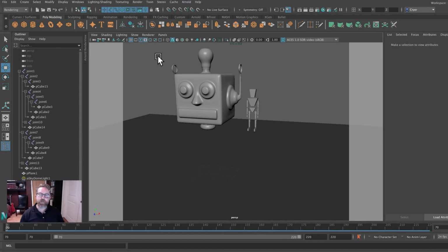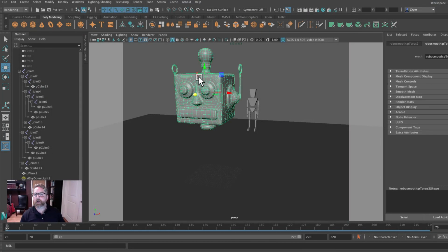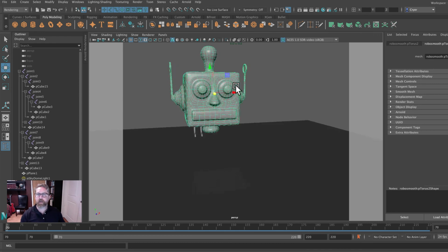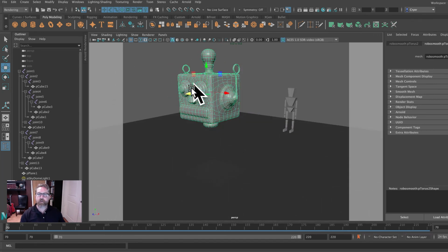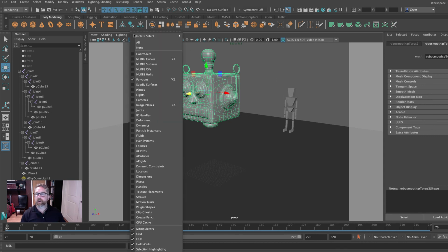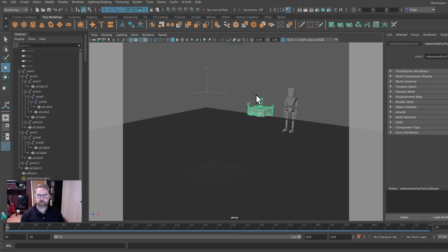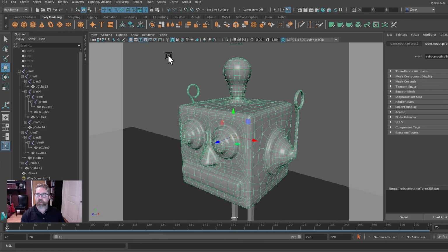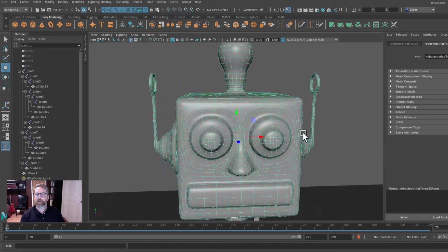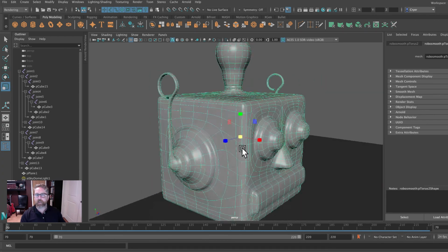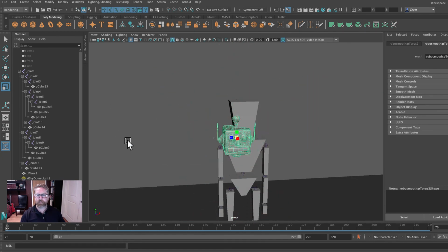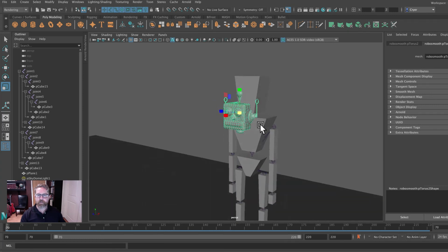Welcome back. So if you have some time to create additional modeling parts, here we've got a continuous surface head, and we can scale this down and have that fit there. We'll bring back our joints so that we have something to snap to. And I'll just snap that into proximity. I'm going to hit the F key and I'm going to turn off my resolution gate. And we have to scale this down to fit. I also am not exactly right on it.